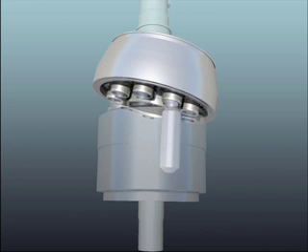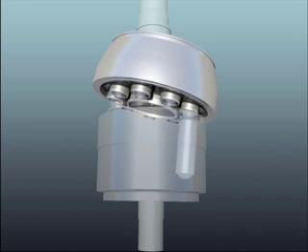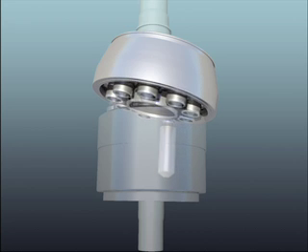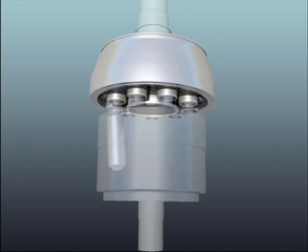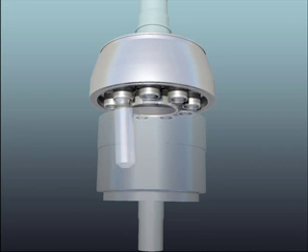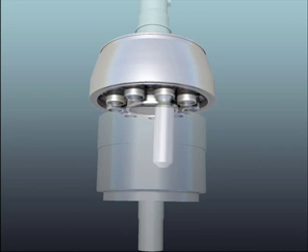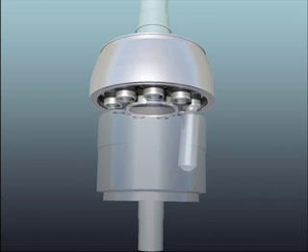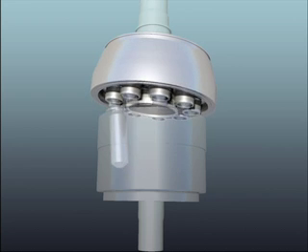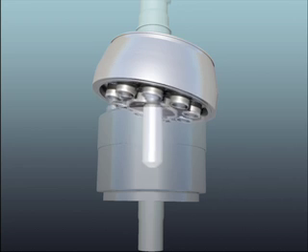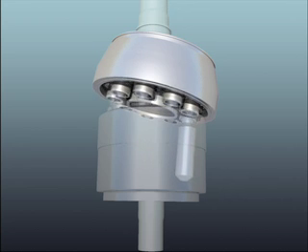In a variable displacement unit, the cam angle determines the amount of fluid pumped per shaft revolution. If the cam angle is set to 0, corresponding to the swash plate being parallel to the axis of rotation, there is no movement of the pistons in their cylinders. Thus there is no output. If the cam angle is set to maximum, the displaced pump volume and thereby the output will be maximum.